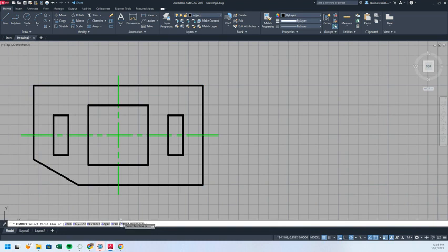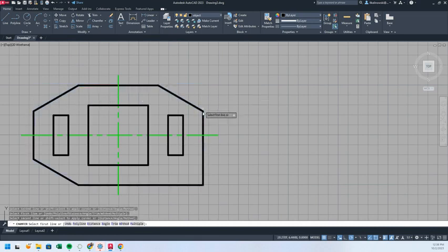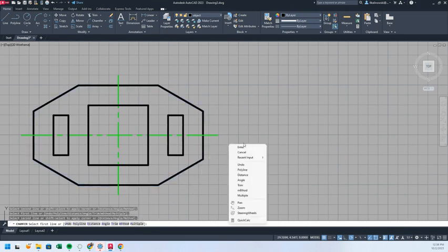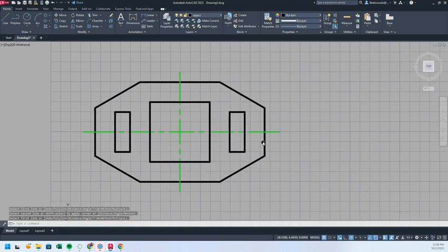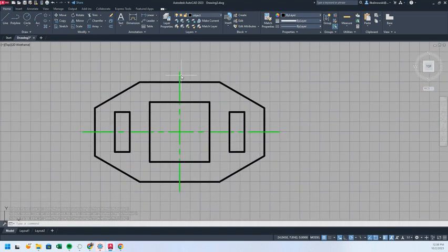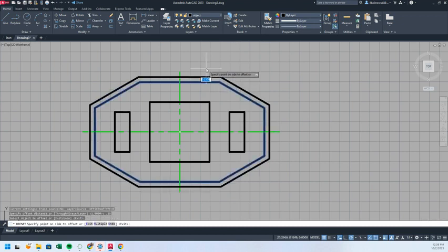So you can continue to do that. I'm going to click multiple down here. And you're going to do long, then short, long, then short, long, then short. Go ahead and we're going to end up dimensioning this, but let's fix these center lines. They should be 1/4 of an inch away from our part. So I am going to offset these lines by 1/4. So I'm going to just go to my trim everything so it's 1/4, and then I'll delete out my outer offset.